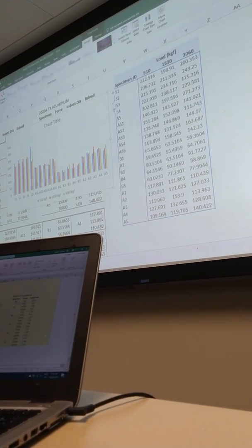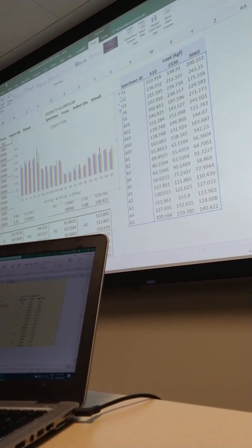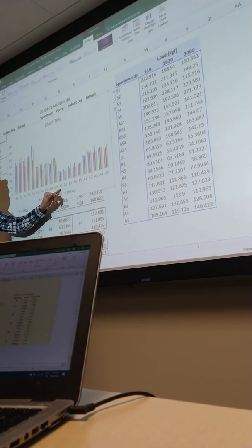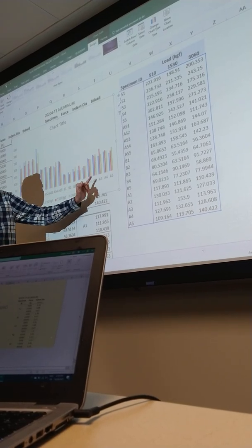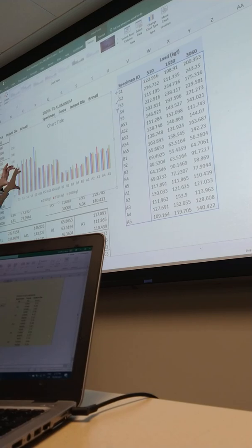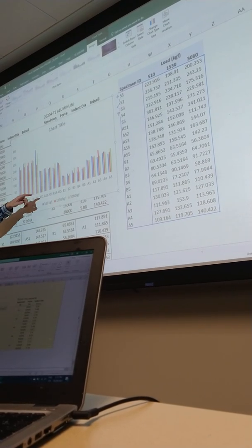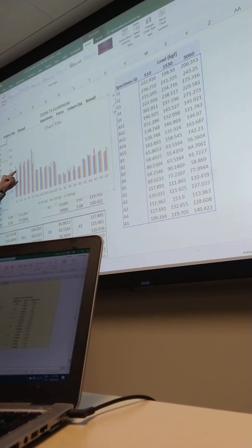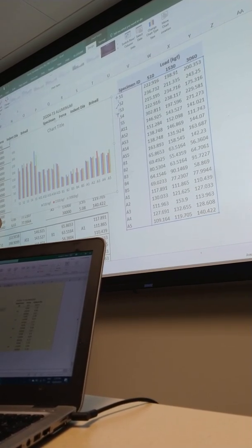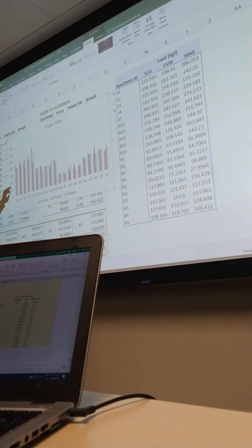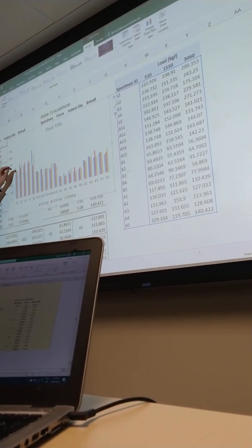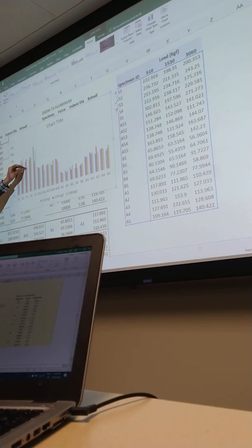And that's it. So you guys can see, now create a bar chart. We have our steel specimens here, our annealed steel specimens here, our brass specimens here, and our aluminum specimens here. You can see when you put 510 kilogram force, it kind of has a little bit higher. Actually, it should normalize. It should be about the same. It doesn't really matter what force you have. You're going to get the same hardness number. So anyways, you should have 3 different hardness numbers for each sample based on the loading.